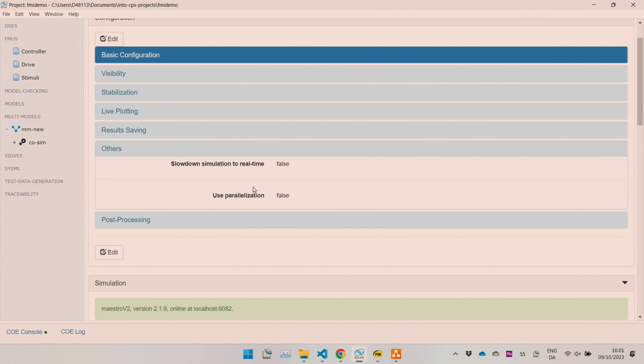That is some background information, because at the beginning we were talking about model exchange, where we have one solver, and co-simulation. And the advantage of co-simulation, if you work together with companies, is that you can guarantee local stability. That is a big advantage. Otherwise, with model exchange, we are normally lost if we want to guarantee anything. So in industry, we normally only use co-simulation.